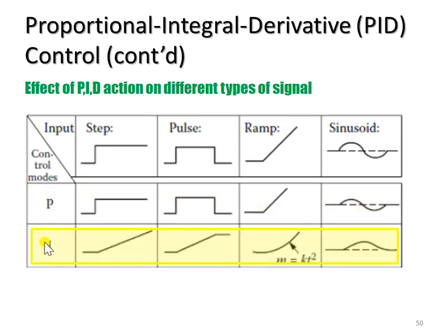Next, we look at integral function, where the integral function will integrate the error over time, which can be simply said the integral function will accumulate the error over time. So we need to visualize the area under the graph will be accumulated over time.